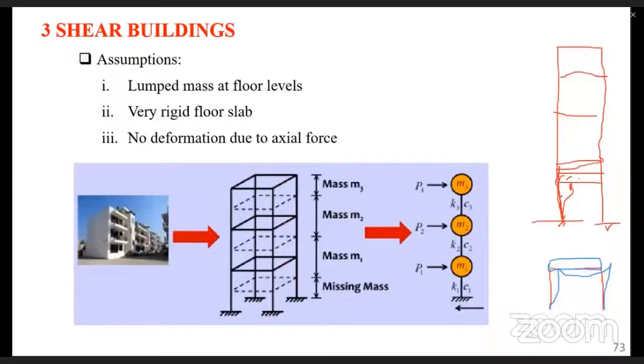But for the analysis for seismicity or for wind loading, what is critical is the lateral loads, and that's what we are analyzing for. Remember, sometimes if we introduce the axial load, the vertical load, which applies some force on the structure downwards, it might be acting as a restoring force. In fact, when you do the design and combine them, they provide what you call the economic design.